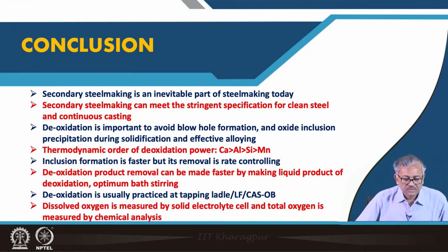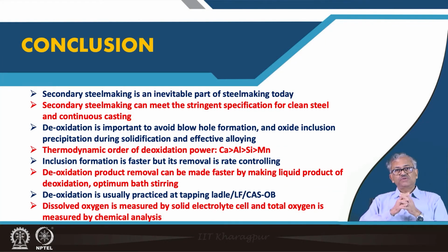And then we have studied the thermodynamics of deoxidation, and there we found that we can lower the oxygen to a very low level, even with 1 weight% of the metal present in equilibrium. If you consider calcium as deoxidant, with 1 weight% calcium in the liquid bath, your oxygen amount can be reduced to 10 to the minus 14 weight%. So a very, very low level, almost zero oxygen.